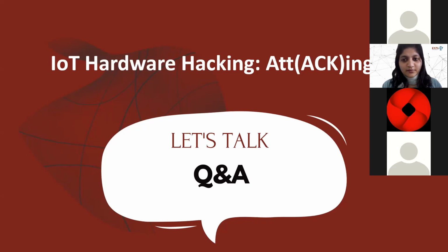So we have one question from Mr. Yashodhan: is the MCU communication always, one second. Almost, you can say not always, but yes, 99.90% it is the case, provided what type of architecture you have. If you have a simple master-slave architecture with one master, it is most of the time like that. If you have a multiple master, multiple slave architecture, it may be possible that one microcontroller can become the slave as well.